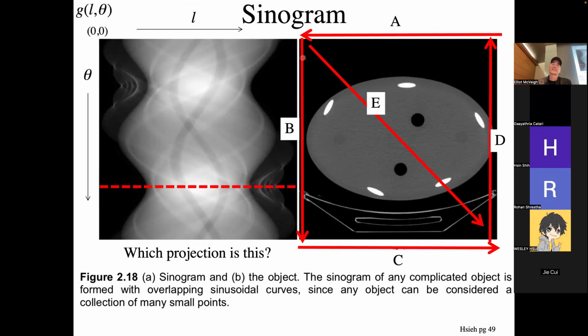If this is my detector, I would imagine the X-ray source to be over here, beaming through the object and then hitting the detector this way. The detector would have little scintillators, like 800 of them lined up this way. Mathematically, we're only going to look at parallel beams. The way you can do that is with an X-ray source that rasters from here down to here and pushes parallel beams through the object.